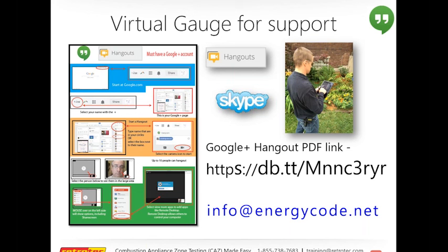In fact, you'll see at the top of the standard, let me read from the BPI 1200. It says for vented appliances, the following combustion appliance safety inspection must be completed to determine if fossil fuel fired appliances are operating safely under depressurized conditions. Then it says ambient CO must be monitored at all times.